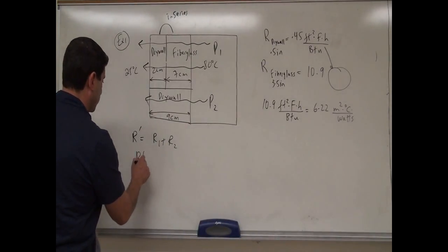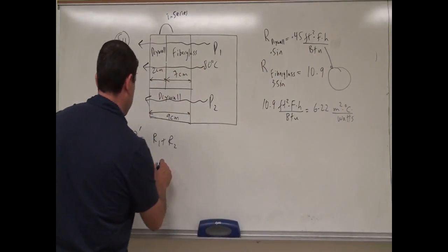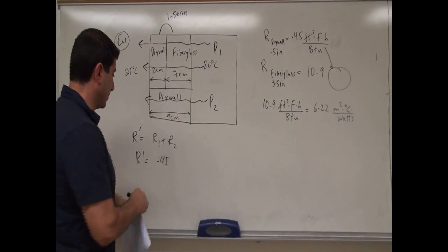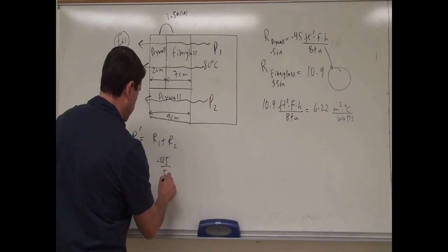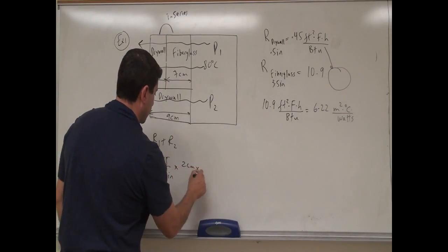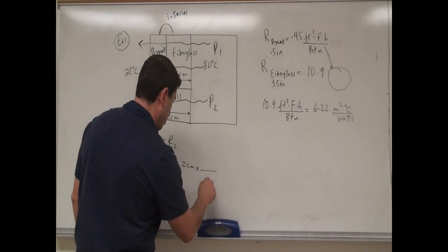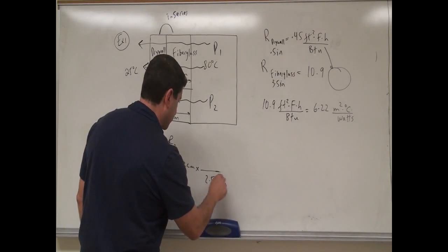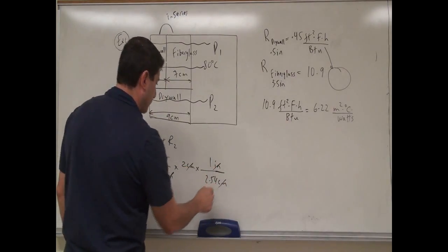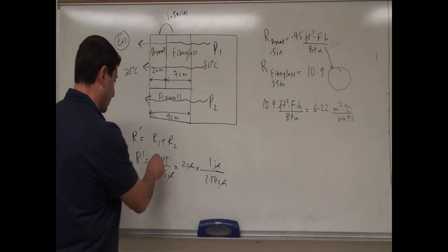So then what is this one here? The insulation factor of the drywall is 0.45. Okay, but that is for half an inch. This one is 2 centimeters, right? So this one is for half an inch. Then you multiply that by 2 centimeters, and then you multiply that by the conversion: 2.54 centimeters is 1 inch. So the inch and inch cancel, centimeter cancel, and then you can calculate what the R1 value is, okay?